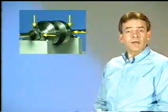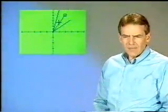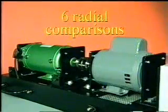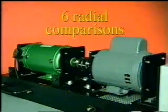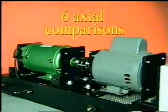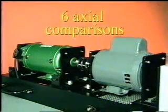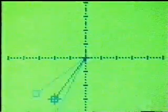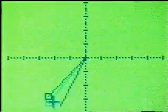Static phase measurements provide another tool for diagnosing many machinery conditions. Remember that because phase measurements provide amount and direction, they can be displayed as vectors to show the machine's motion. Use the 6-phase comparisons in the radial direction and the 6-phase comparisons in the axial directions. Be sure to take into consideration the orientation of the sensor. The directional phase comparisons, as well as some erratic phase conditions, point to specific machinery faults.